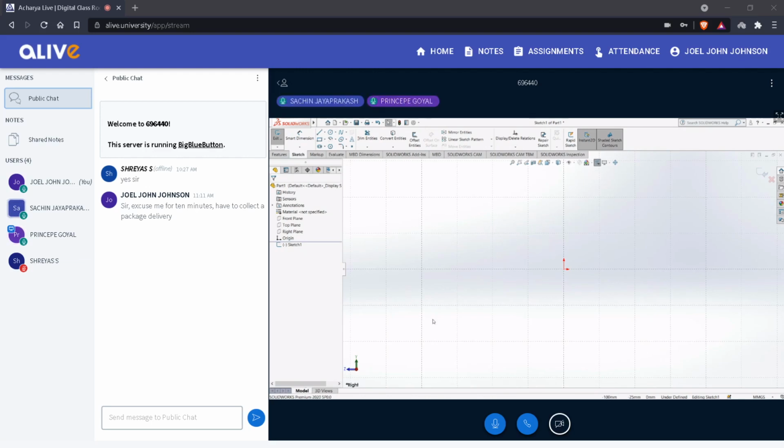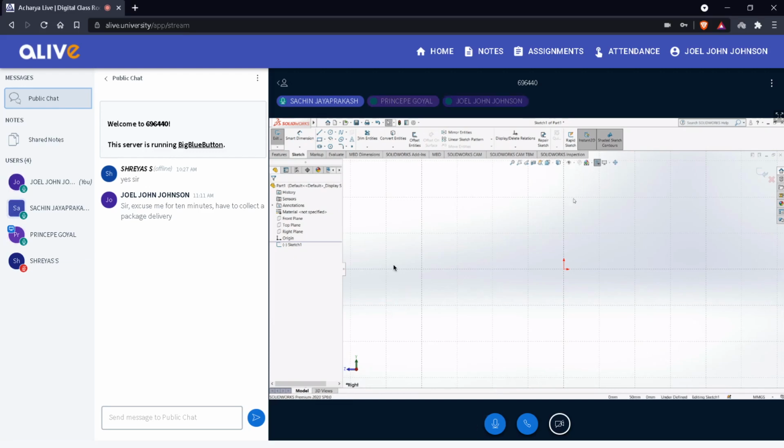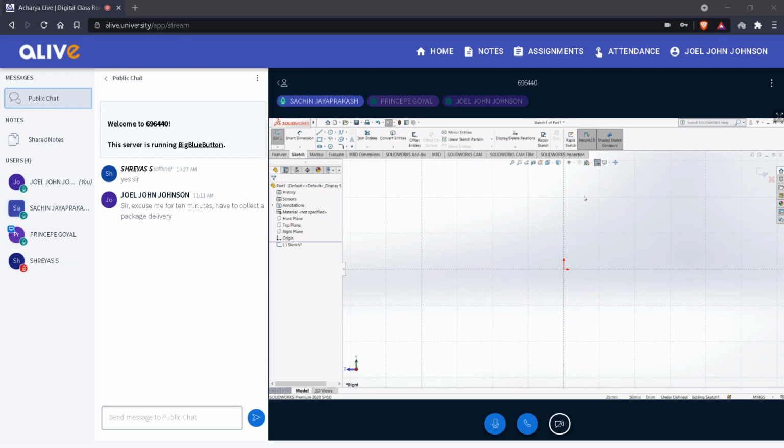Okay, for quick settings, I mean for the snap settings that Joel asked about, initially you'll have to switch on the grid snap from the setting itself. And later, if you are using certain tools, in that case, this quick snap tool, like select any line tool or anything. Next to that line tool. Yes. Now you can see that it is on, right, Joel?